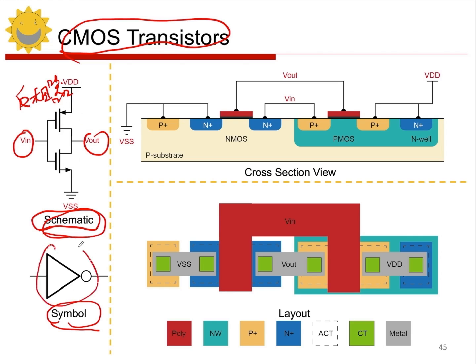Next, we have the layout. This is what the layout looks like. It's a multi-layer drawing. So, what is multi-layer? It consists of many layers, right? There are layers for poly, N-well, P-well, N-source, contact, and metal. So the entire layout looks like this. Actually, this part on the right is the layout for a PMOS. From the process flow we just discussed, I believe everyone should have an idea of what the PMOS layout looks like.